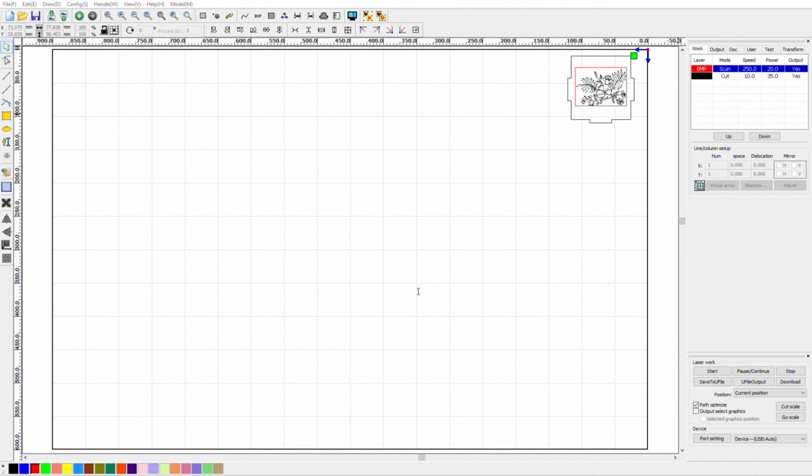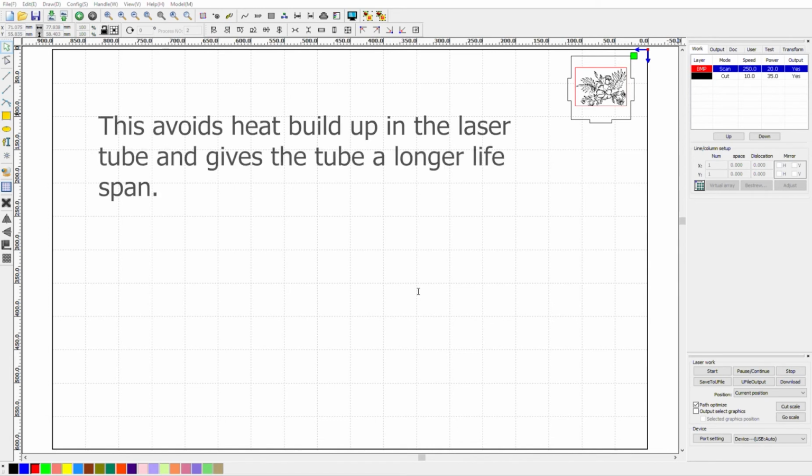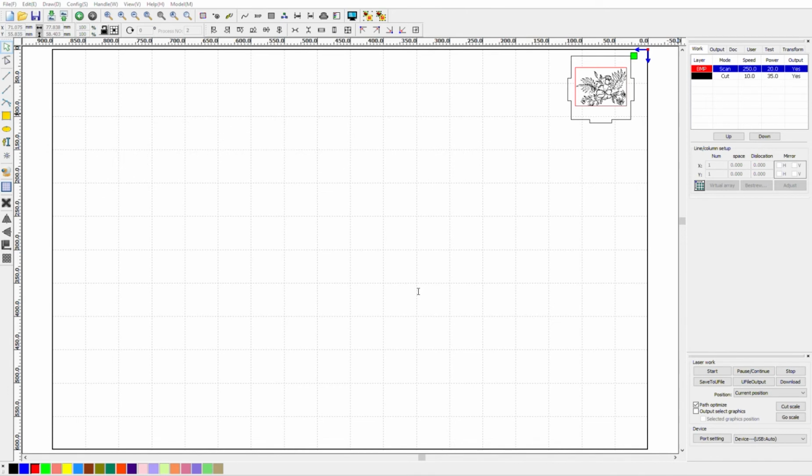You may have also noticed we cut almost everything at 35% power and then just adjust the speed for different thicknesses of materials. When cutting, too much power or too little speed is better than the other way around. You won't burn the part, as once the beam vaporizes a volume, there's nothing left for it to interact with to cause more heat. But if you undercut the part, unless you figure it out without moving the sheet on the table, it's usually going to wind up as scrap.